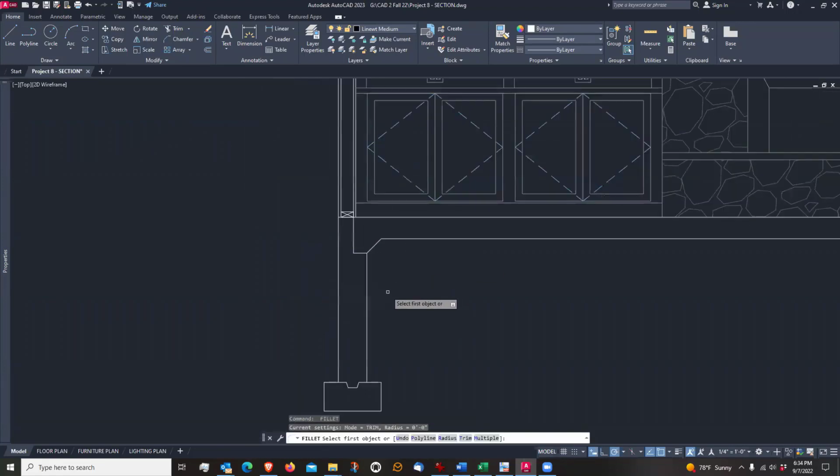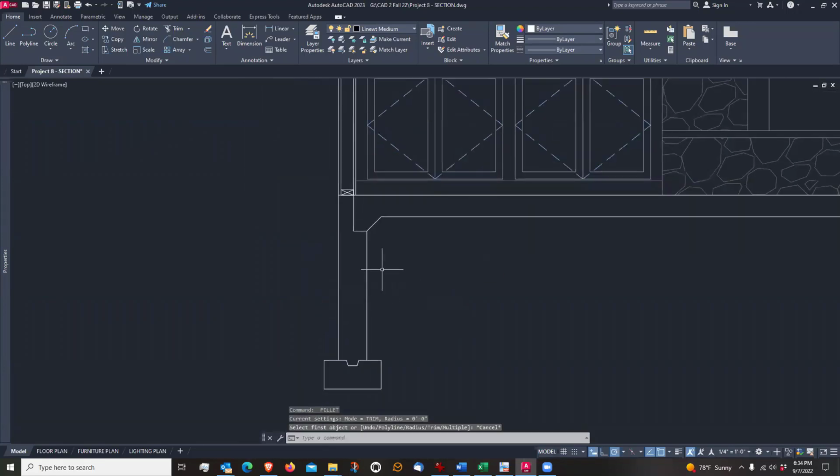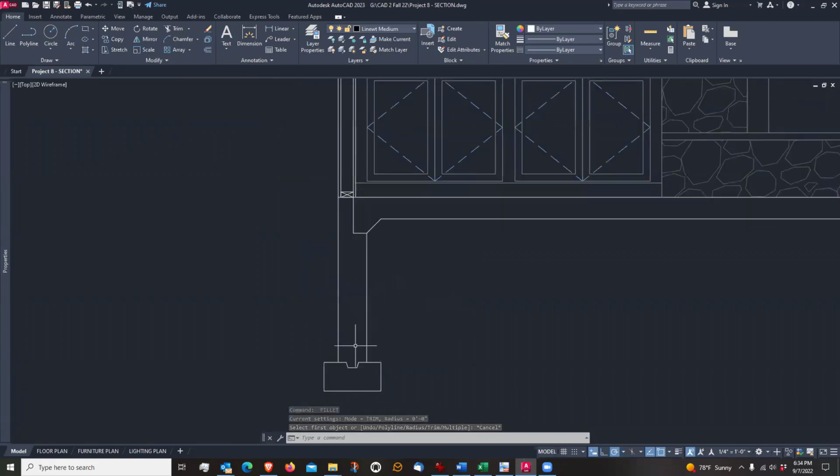Okay, so what's going on? What are we drawing here? Well, this is the foundation wall, and the foundation wall has a little flat part on it, and then it extends up here. So this extends up, and they can put the studs on the top of the foundation wall, and then the weight of the stud wall is carried down into the foundation.